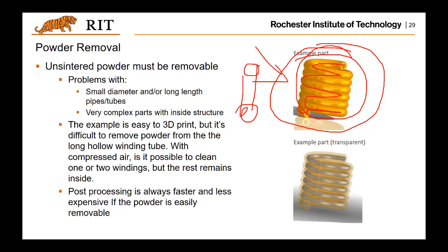And after quite a long build time, he came back to the lab and took out the part, and he found quite a bit of liquid resin trapped in the center of the part, because he didn't consider how this excess liquid resin would be removed.